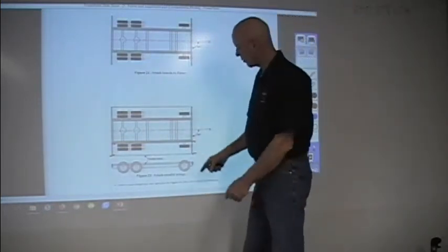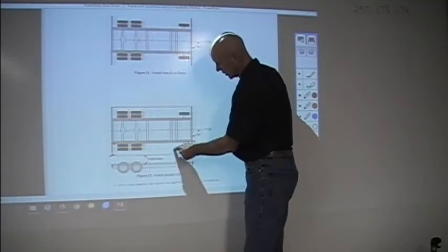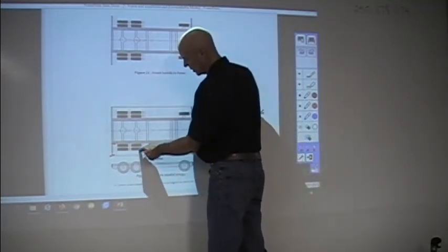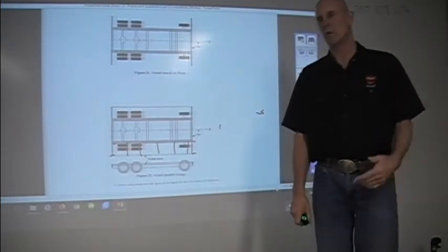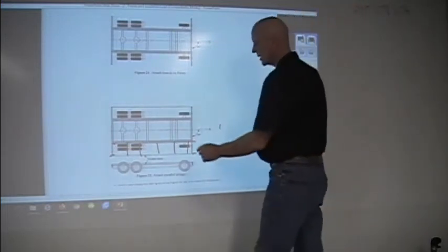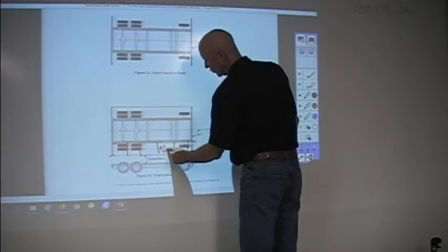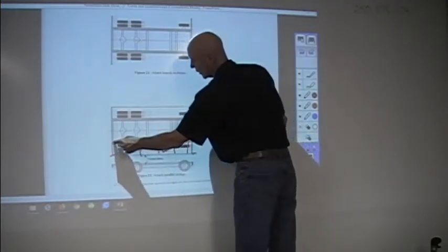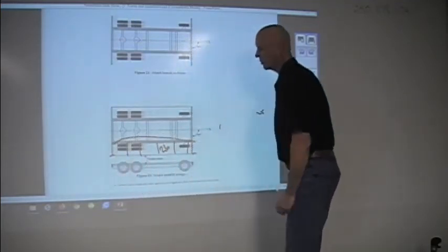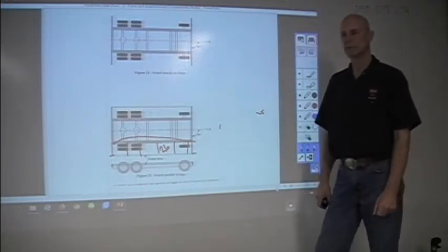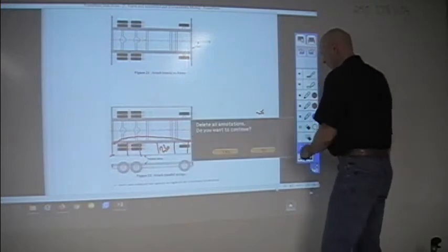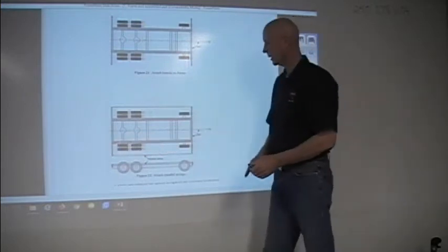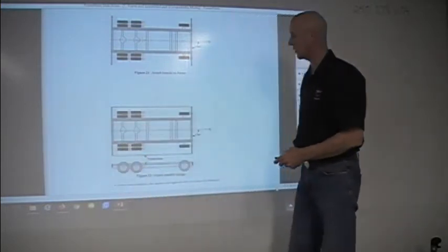Then I'm going to go along with the tape measure, and I'm going to measure at different points from the string line to the frame. All of those should be 24 inches. If I end up, let's say right here, I end up with 26 inches, I know that my frame is bowed that way. If it's 23 inches, I know it's bowed the other way. And can that be straightened? Yep. And we can do that on a frame machine.